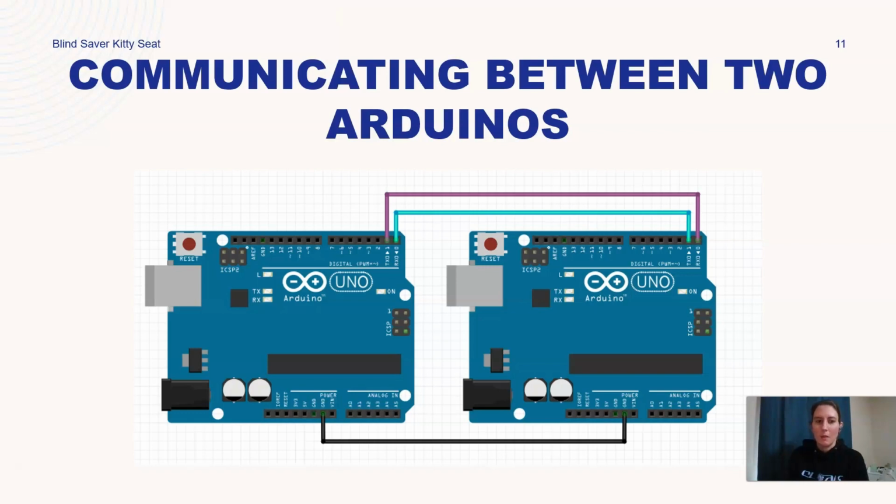So I wanted these Arduinos to be able to communicate with each other instead of just relying on delays. So what I did was I connected the Arduinos through the transmit and receive lines, which are digital pins 0 and 1 on both Arduinos. And you have to make sure that you ground the two Arduinos together.